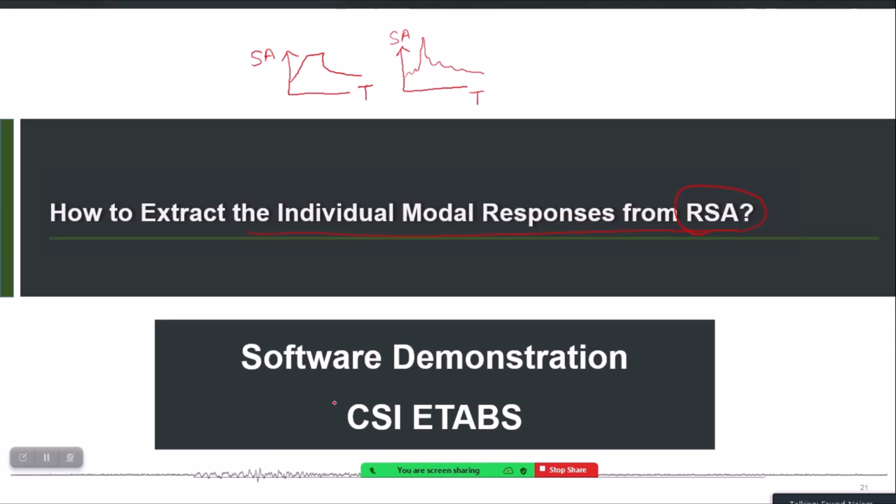the program calculates the equivalent static forces for each mode, the Fi vector for each ith mode, applies that vector as a static force vector, and then determines the response, for example Ri for each mode, any ith mode, and then combines those responses using either SRSS or CQC to get the overall peak response. But that response will essentially be static because the equivalent static forces are not the dynamic forces, they are the peak estimates of those dynamic forces, so they are static.